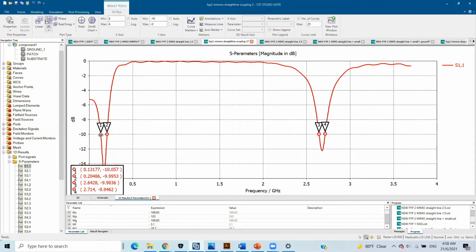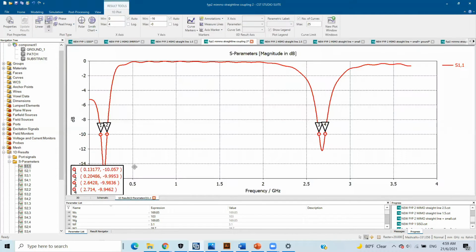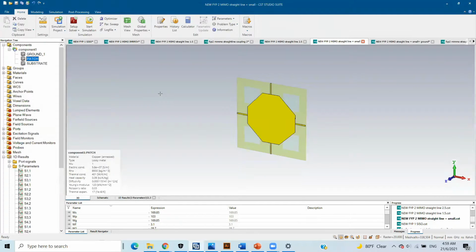When I was studying theory, I noticed that we can shift the operating frequency of the design by making the patch smaller. When we make the patch smaller, the operating frequency tends to shift to the right a little bit, which is what we want. So this is what I came up with. I scaled the design and reduced it 10% smaller than the original single input, single output design, and I also added an infinite number of stepped corners.